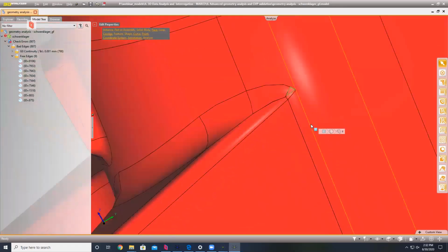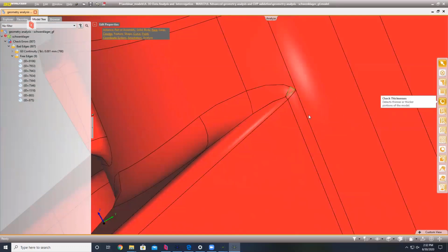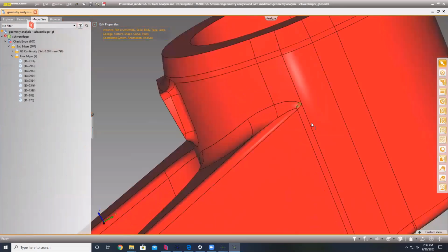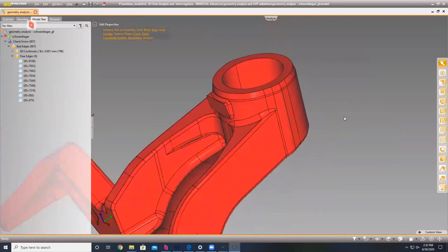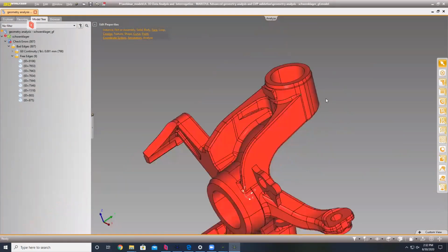At this point in 3D Evolution, you will heal it using the healing tool. Or in here, it helps you document it. You can create an HTML file or a 3D PDF file showing this, so you can send it back to your supplier or the producer of this file. You tell them, hey, there's a problem, I need you to fix this. This is exactly where it is.